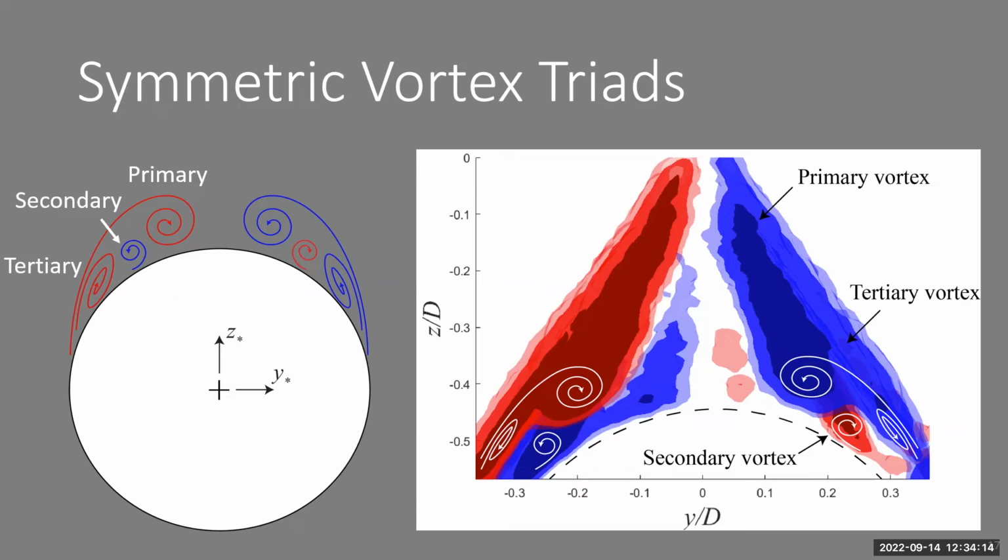On the right-hand side is an isosurface plot that is composed of 34 measurements along the length of a cone that are half a centimeter apart. Values in between the measurement planes are cubically interpolated. And this just serves as a visual aid as to what this vortex system looks like from behind.